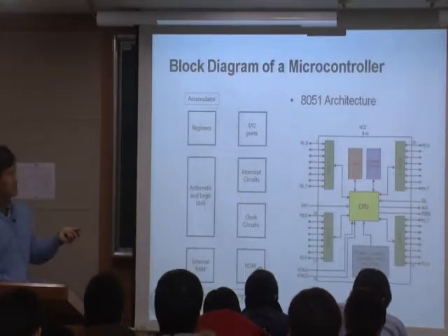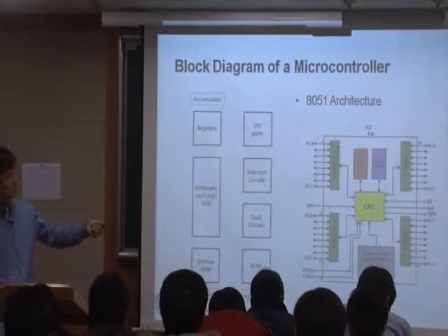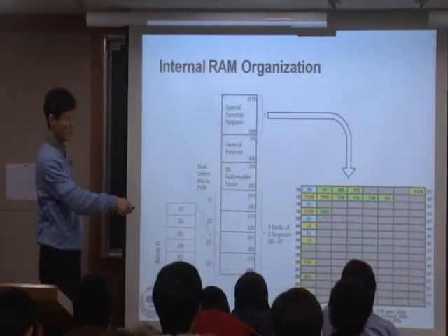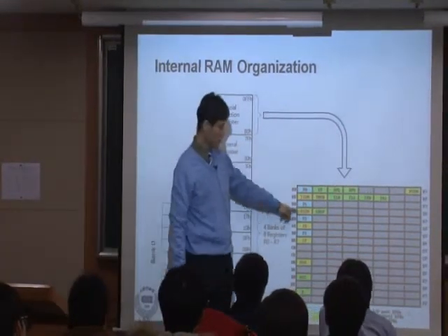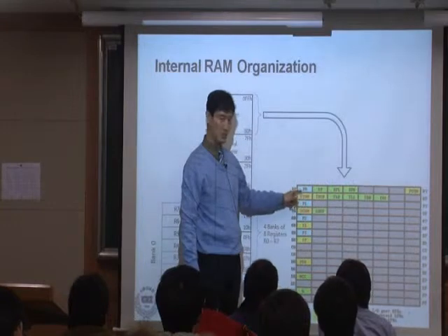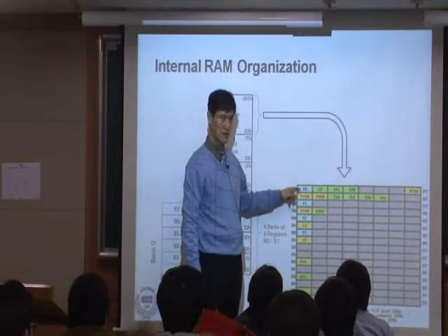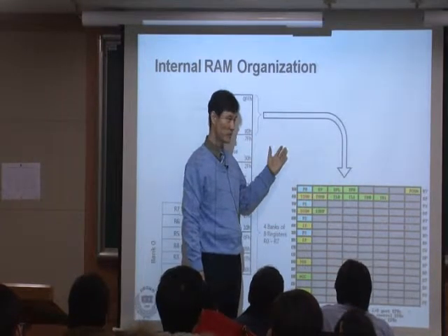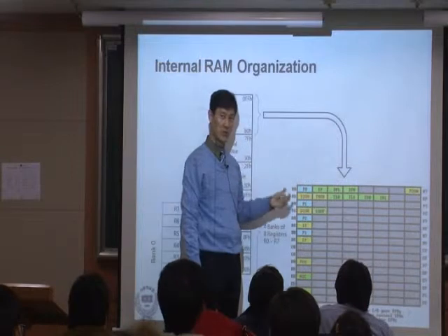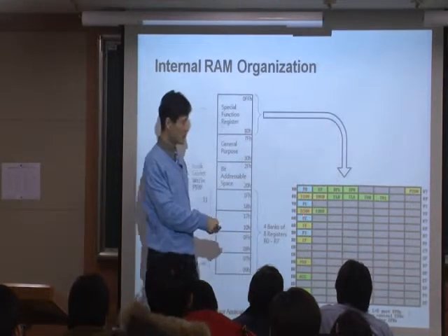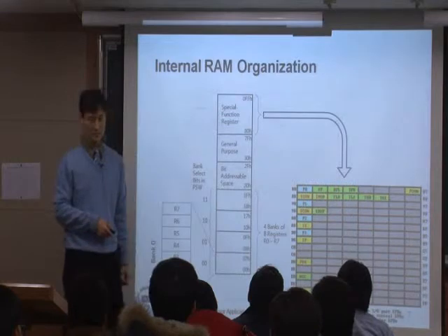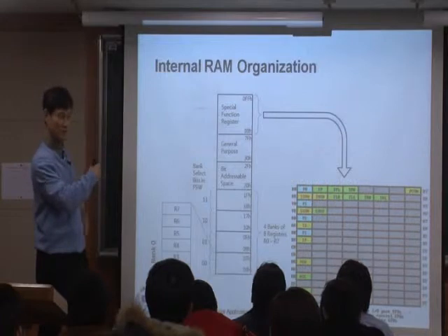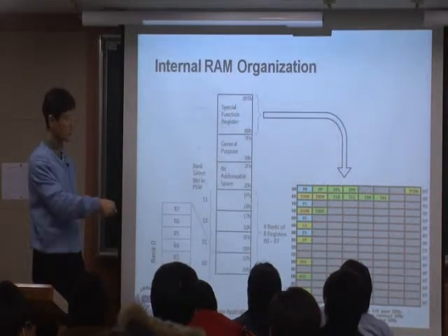Okay? So those are the ports. In 8051 we have 4 different ports, right? So therefore we need 4 registers, P0 to P3. Then why do you need a register for each port? P0 is the register for port 0, P1 is the register for port 1. So why do you need P0, P1, P2, P3? Simply think about it. We already have the port hardware. So what do you need the register for?